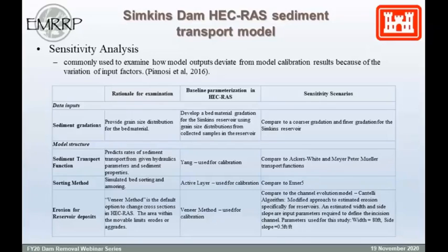And for this sensitivity analysis, I picked a width of 80 feet and a slope of 0.5 feet over feet based on cross sections farther upstream from the reservoir that were not impacted by the reservoir. So I assumed that the incision channel was going to look similar to the cross sections farther upstream.